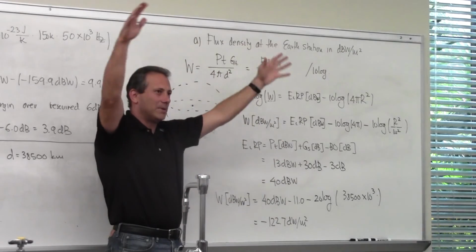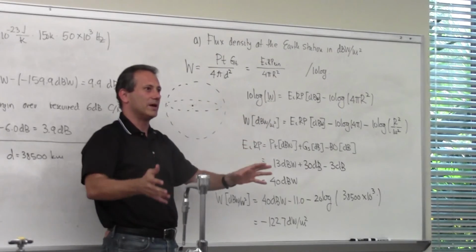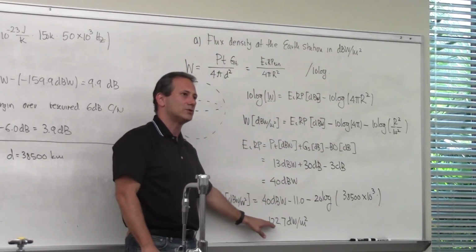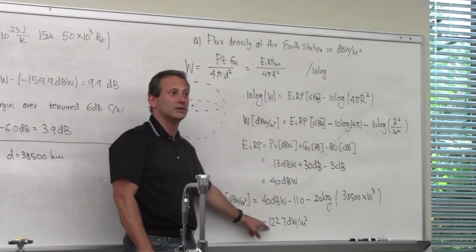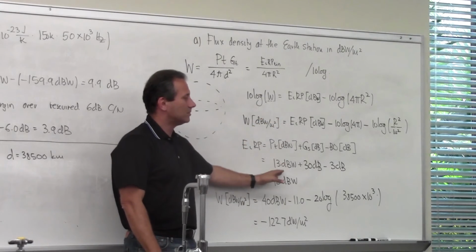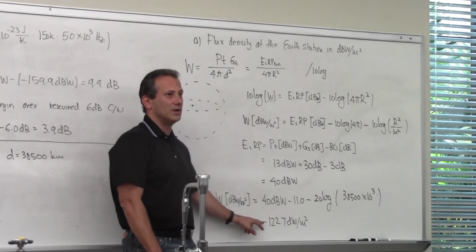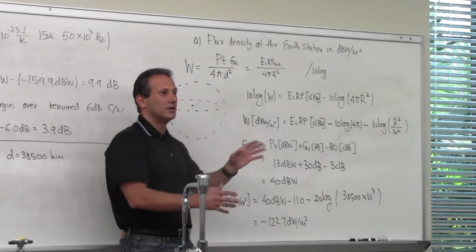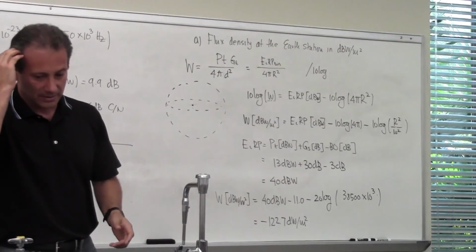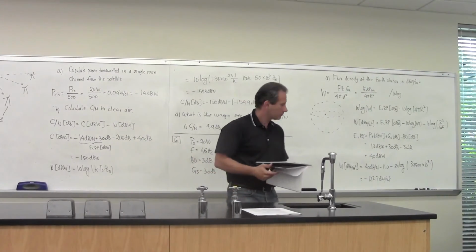Antennas are about a meter squared, a bit smaller or a little bigger, but that's the order of magnitude. If this was into an antenna with an effective aperture of 1 meter squared, this would be exactly the power. Why am I telling you this? Because if you mess up the units, chances are you'll get something like minus 160 or minus 35, which is unrealistic for the power, and therefore unrealistic for your power flux as well.